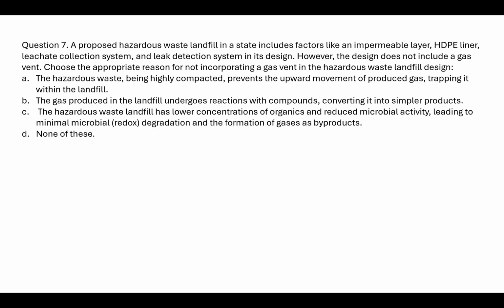But in the hazardous waste landfill, the hazardous waste has very little organics. That's why the microbial degradation is very less, so these gases will not be formed. So there are no vents for collection of the gases. So, C is the correct answer.